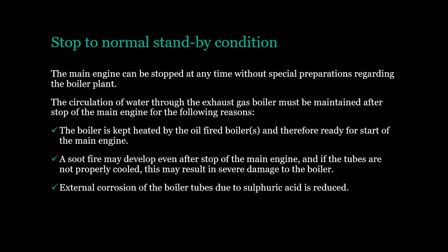Stop to normal standby condition. The main engine can be stopped at any time without special preparations regarding the boiler plant. The circulation of water through the exhaust gas boiler must be maintained after stop of the main engine for the following reasons. The boiler is kept heated by the oil-fired boilers and therefore ready for start of the main engine. A soot fire may develop even after stop of the main engine, and if the tubes are not properly cooled, this may result in severe damage to the boiler. External corrosion of the boiler tubes due to sulfuric acid is reduced.